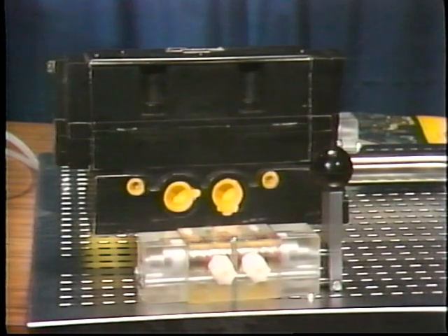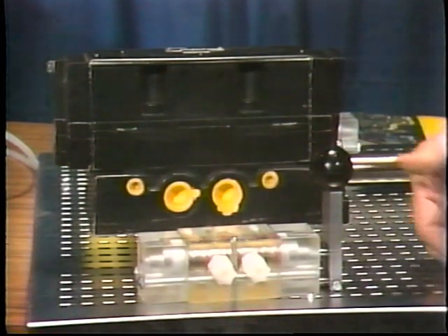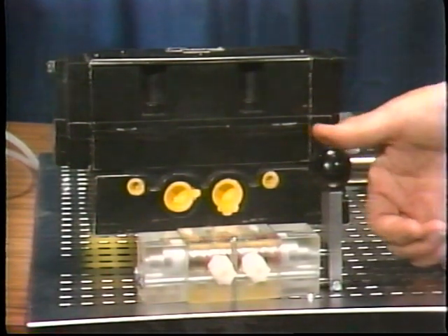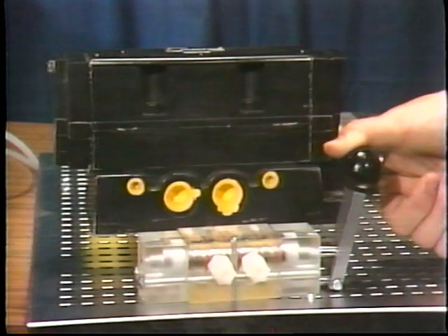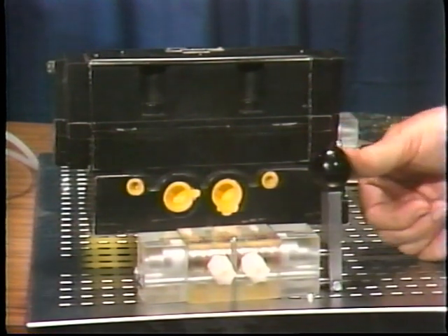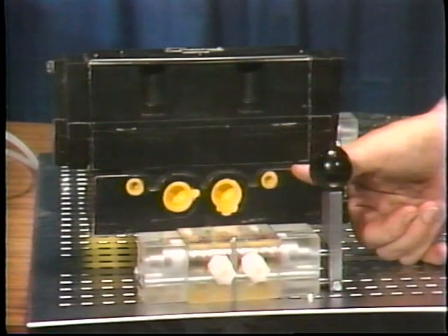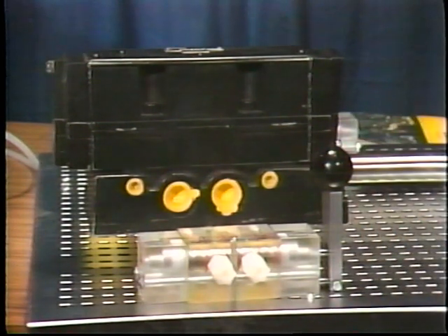We've already shown that the 2 extreme positions of a 4-way directional valve are related to the actuator's direction and could be referred to as the power positions of the valve. The center position of a 3-position directional valve is used to satisfy a system requirement. For this reason, the center position is called the neutral condition.